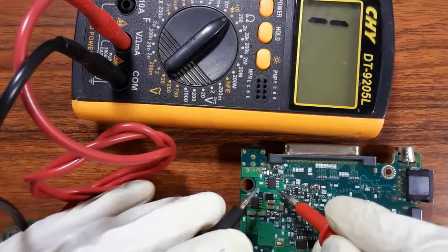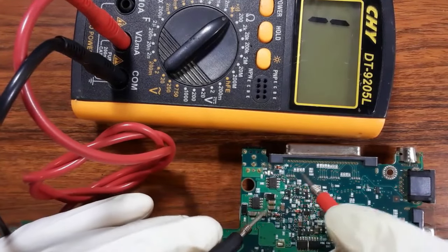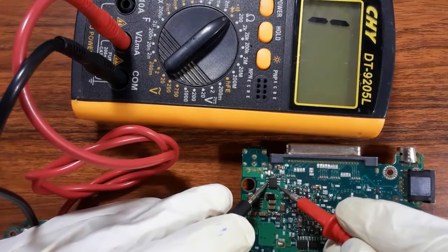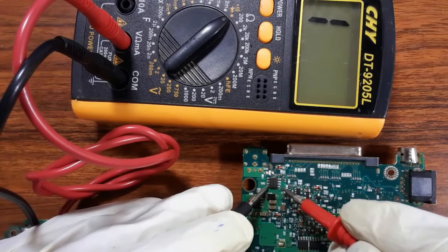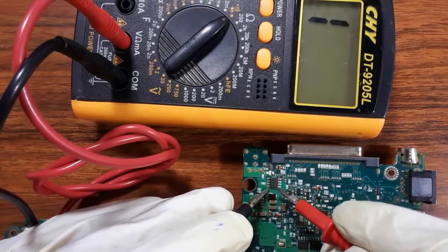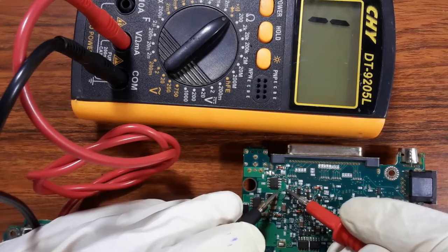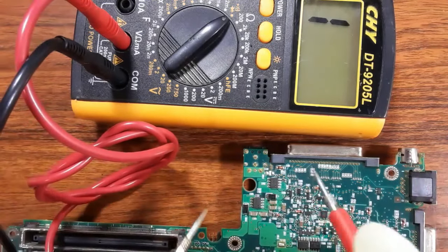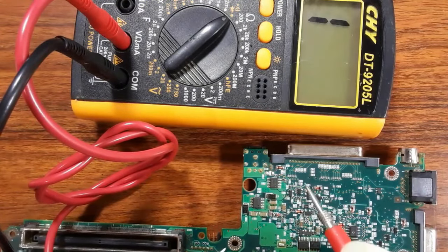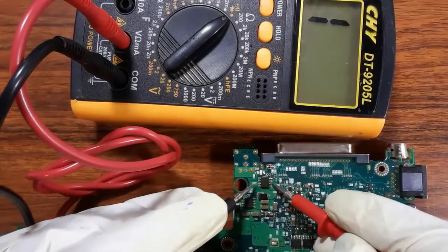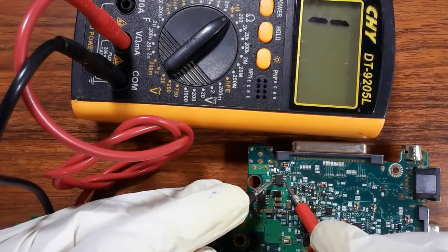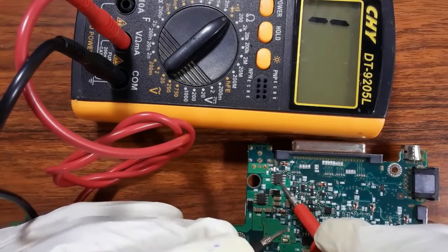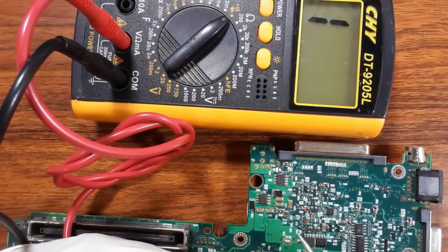Of course, you can check the MOSFET using the multimeter. You should check between source and drain, and between drain and source, and between source and gate, and also between drain and gate, etc. But the fast checking for the MOSFET is between source and drain, like this. If you find a continuity, means the MOSFET is bad. If not, then the MOSFET 99% is good.